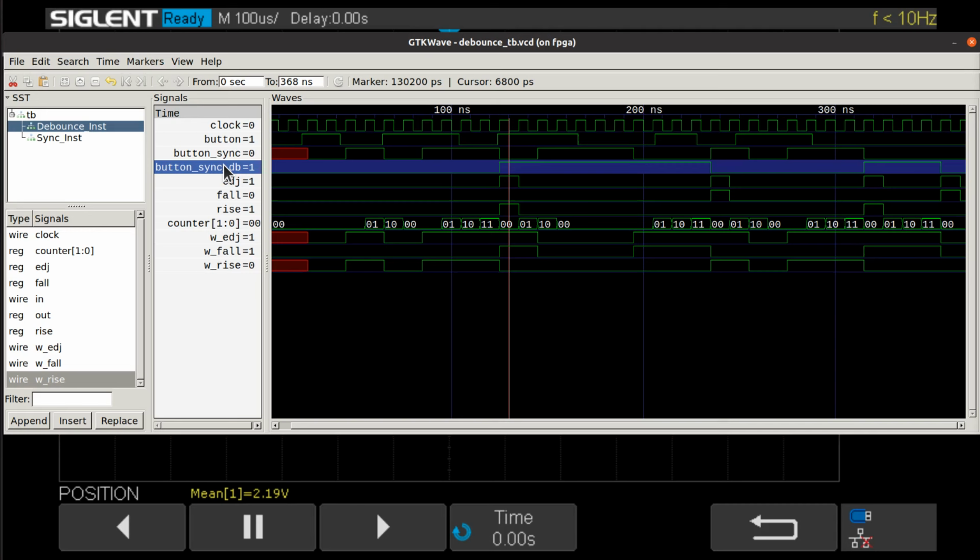So what am I getting at here? Sometimes you have synchronizers between two of your own circuits that cross clock domains. They're not just used to bring in signals from the outside world on the pins of your FPGA. So the value, of course, would be if your synchronizer uses fewer LUTs than the counter that you need to do your debouncing, then maybe you'll be ahead of the game.